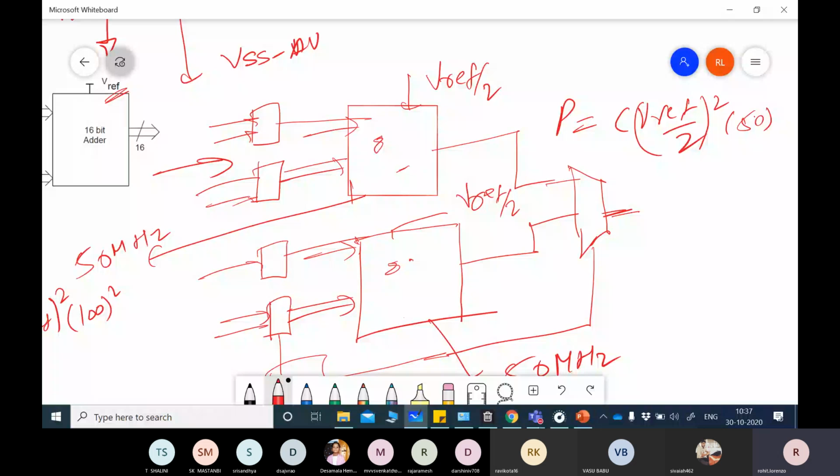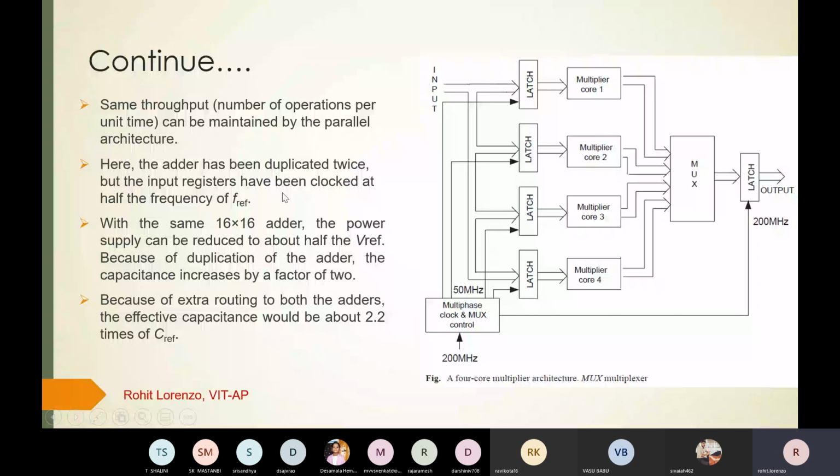Okay, so this is there in parallel processing, and actually here is a figure for multiple cores. So this is also a multiple core system. I will change it later. Here also, like suppose several latches are there and multiple cores are there, and they are operating separately, block wise. So whatever the power dissipation is related to the block, if this block is in operation, power dissipation will be there, and if these blocks are not in operation, power dissipation is due to only one block. So blocks that are operating are the only ones responsible for the power dissipation.